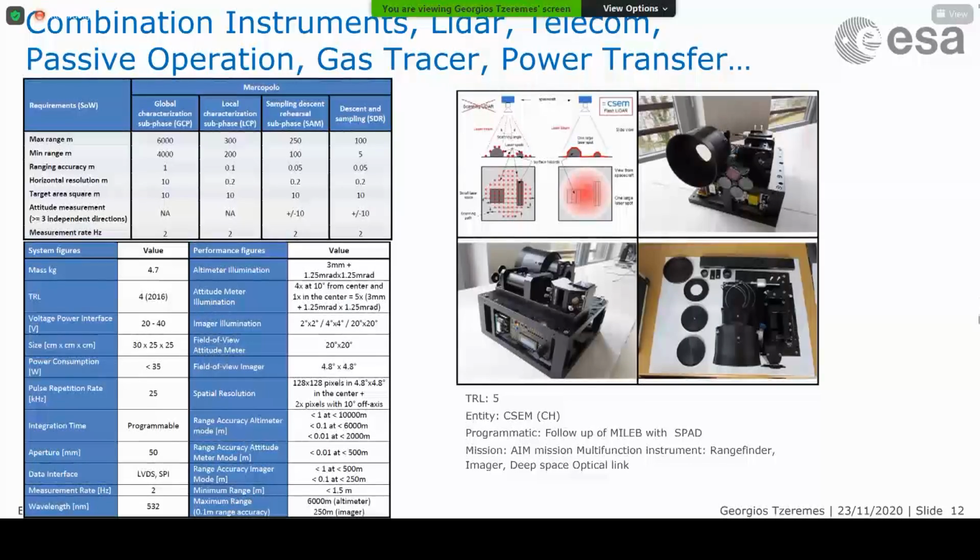the platform to Earth. The difference between this system and the previous ones is that, as you can see in this photo, what we typically do with the previous systems is we scan, and then we have two mirrors moving, and then we get a very quick representation of the area of interest. With this technology, we emit a couple of pulses, and then we take the return. We sum the return, and it's like a flash camera photography. So they're called flash LIDAR systems.